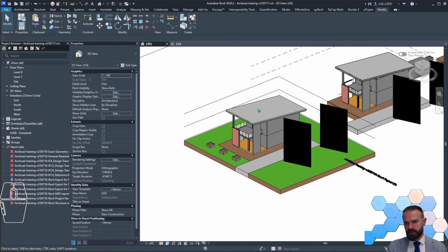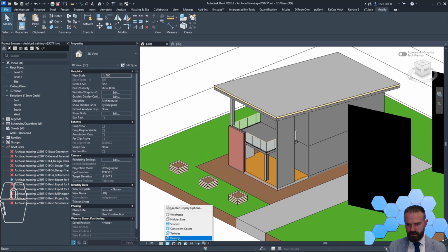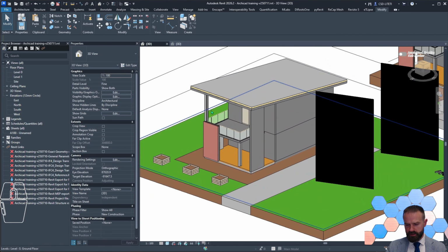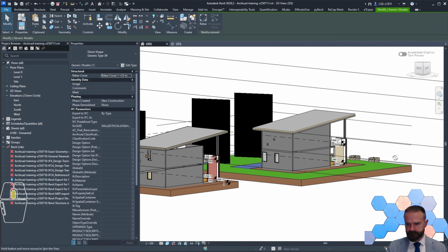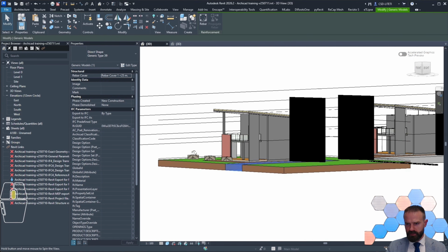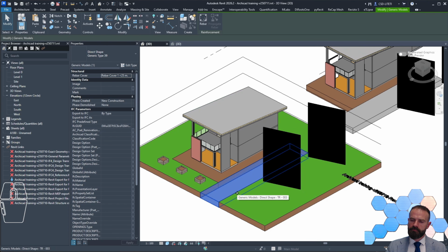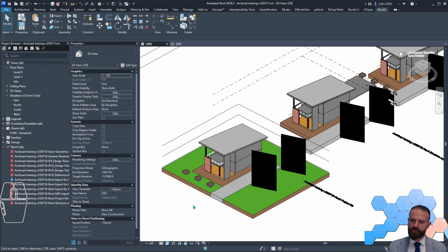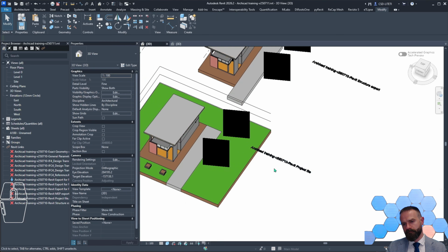And if you want to bring all the colors and all other textures that are not converted, but the basic consistent colors and the exact geometry of all the components, so you should request from architects who are modeling in ArchiCAD, so they export the model in this Revit project file type.